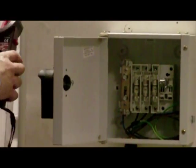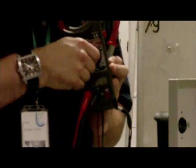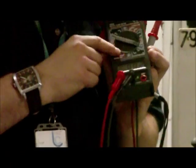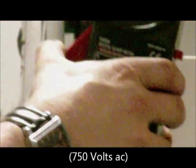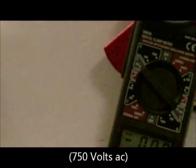As we've previously discussed, we need to put it on the 750 volts with the sine wave symbol. You can see there it's reading as 0. Check again that the leads are intact. It's got finger guards fitted, and it's got tips with the exposed part of no more than 2 millimeters.